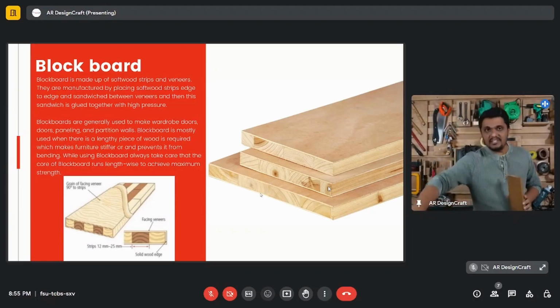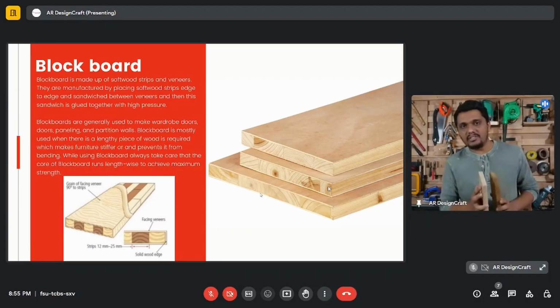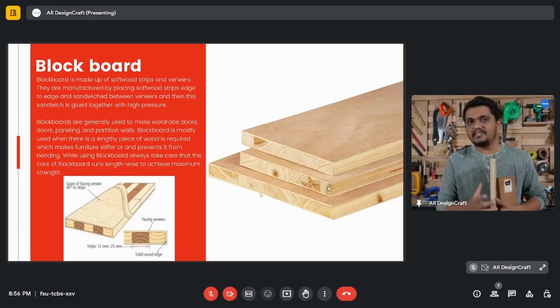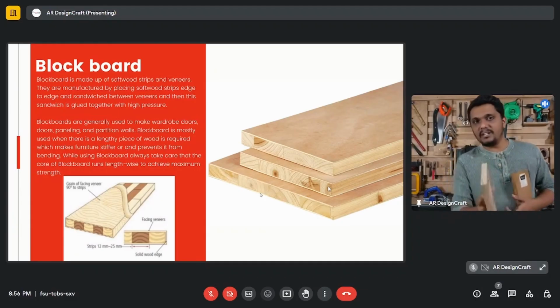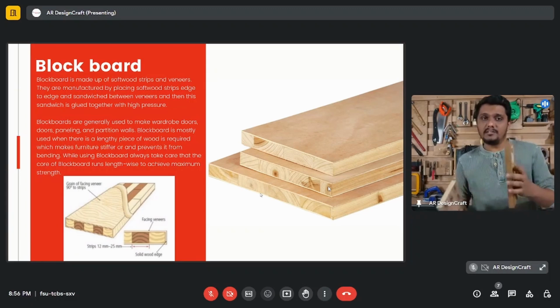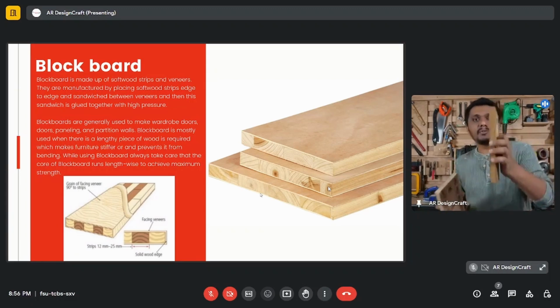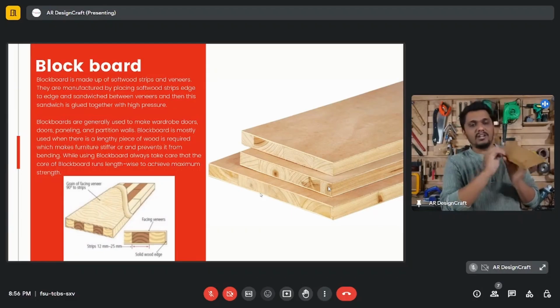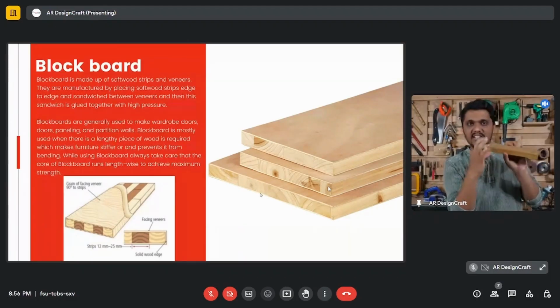So like we were discussing, right? Second point जो था plywood का कि वो bend नहीं होता है. And I said that it depends on what the plywood quality and the material, the glue and all those things, right? Other factors is there to decide whether it will bend or not, right? So plywood is again prone to bend. That is why they use, in place of plywood, blockboard which will not bend. Why? Because there are strips of wood, not layers of wood. Strips. मोटे मोटे इतने जो thickness है ना, यही thickness का अंदर strips है. You will see that.